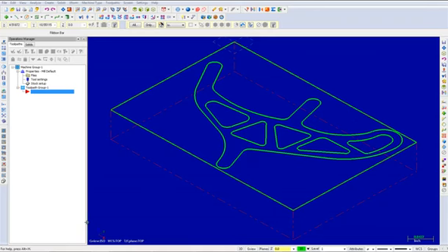In this video, I will show you a 2D high-speed dynamic area mill toolpath. This toolpath is used to machine pockets using a smooth, clean motion. 2D high-speed dynamic milling toolpaths utilize the entire flute length of their cutting tools to achieve efficiency in milling. They are designed to maximize material removal while minimizing tool wear. You are going to use ISCAR HEM tools.